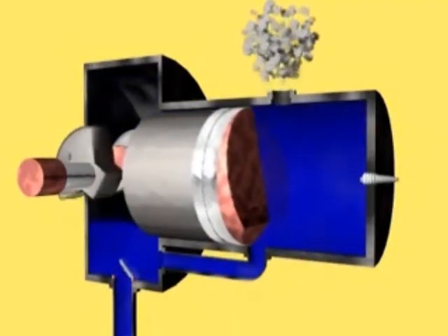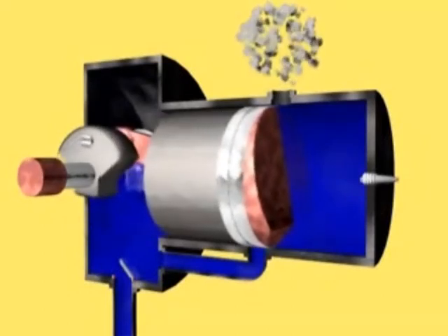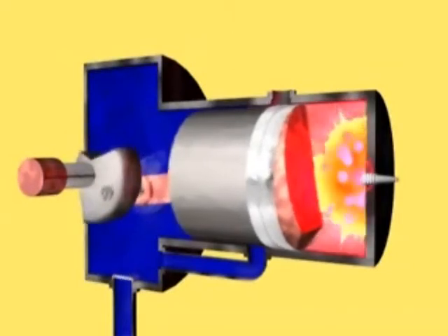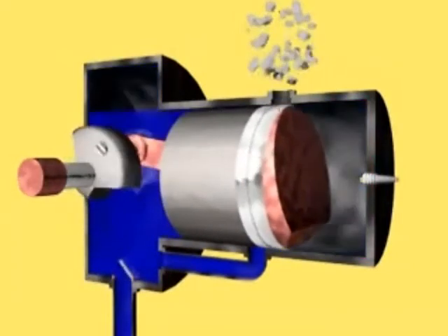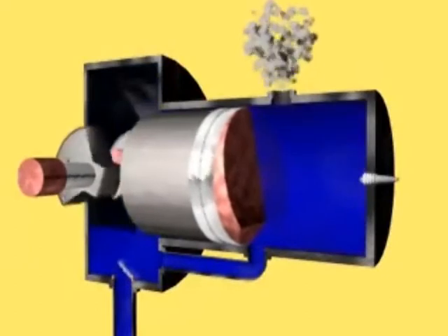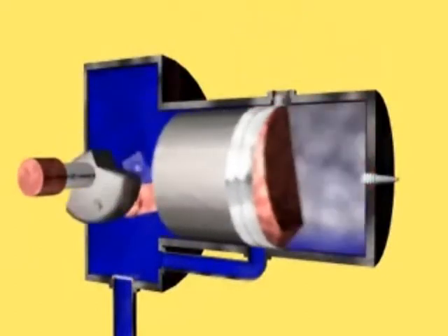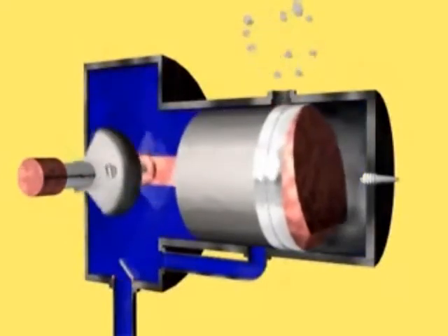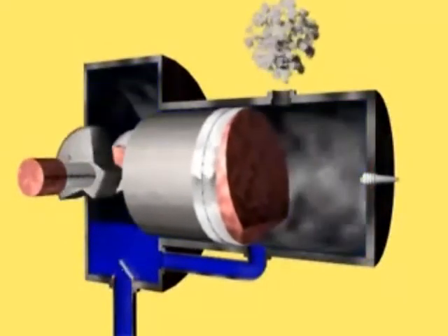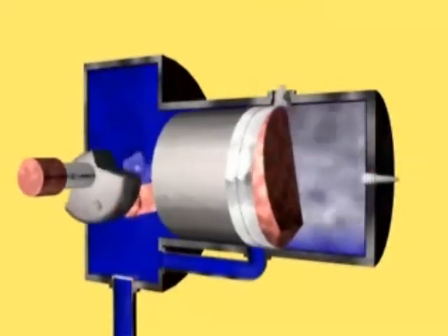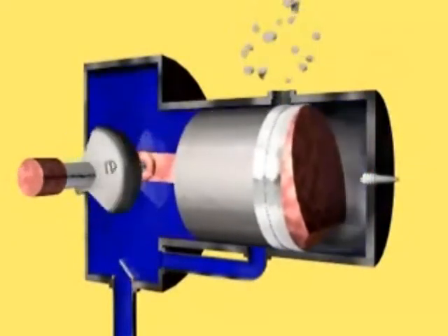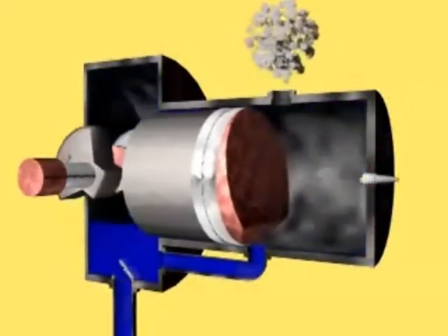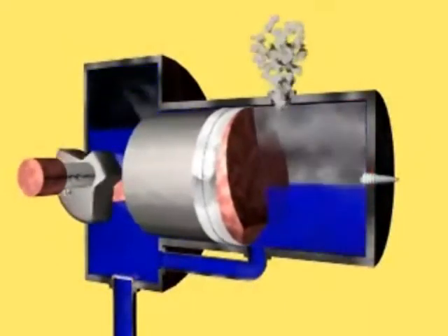Now the piston starts moving back toward the spark plug, compressing the air and gasoline mixture so the spark plug can fire again. This cycle repeats thousands of times per minute. You can see that the piston is doing three things besides being a piston. It's an intake valve, an exhaust valve, and a compressor. Because the piston is doing so many different things, it makes the engine incredibly light. You can also see that the spark plug fires once for every rotation of the crankshaft. That's twice as often as the spark plug fires in a four-stroke engine.